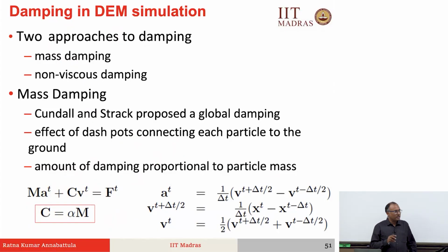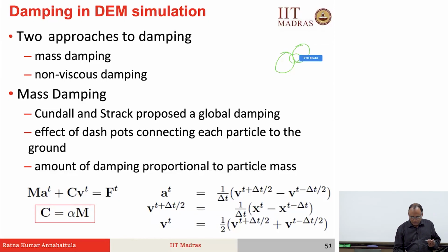When you are dealing with pure elastic contact, you are not really talking about dissipation of energy in the material. If you are only talking about pure elastic contact, there is no dissipation that you can put in the contact constitutive law. However, in reality, although I am only modeling two spherical particles and we are thinking that they are atomically smooth, when you zoom in, the surfaces look like that, and when this surface is interacting with this surface, the local contact area is very small.